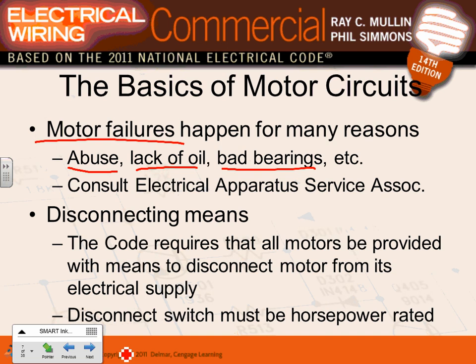So all these are a big deal. And also consult the Electrical Appliances Service Association. There's a lot of information about the appliances and the motors, guys, that comes from the manufacturers that you have to follow. How often do you have to change the oil? How often do you have to oil them? How often do you have to tighten the V-belt, torque them, align the V-belt? So tons of information. I'm not going to skip on the motor failure, just FYI.